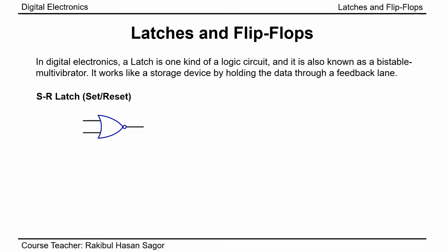On the other hand, if we know that one of the inputs of the NOR gate is 0, we cannot say what the definite output is unless we know the second input. If the second input is 0, the output will be 1. If the second input is 1, the output will be 0.